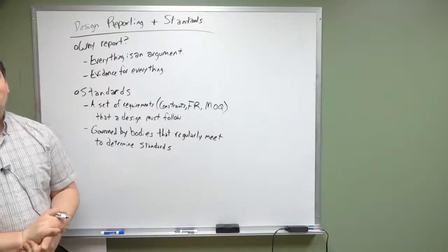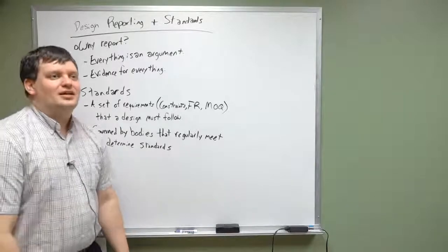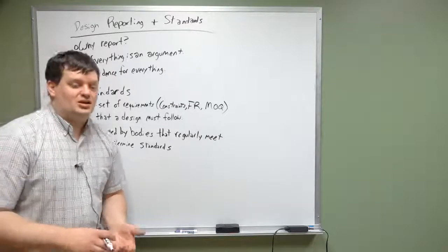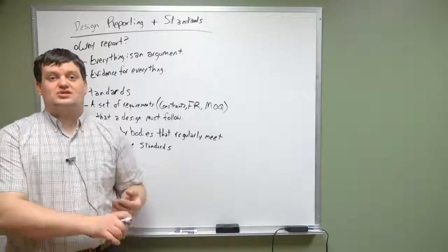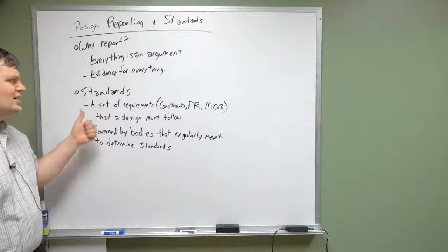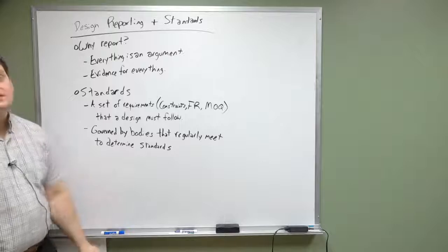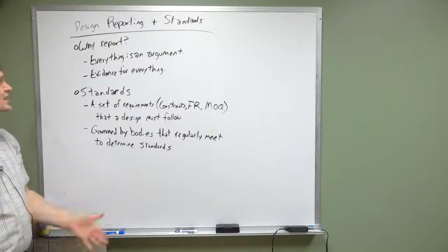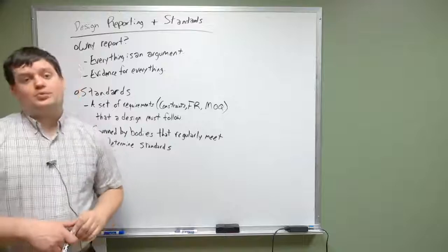So you can't just say, oh yeah, that's a 45,000 pound bolt. How sure are you of it? No, I'm not sure at all. You can't say that. You can say, okay, look at my testing standards. Here, we did testing on bolts from the same batch. We discovered here are the stress strain curves for them. It experiences this peak amount of stress. They actually have that reporting built into these standards to be able to prove evidentiary that it follows the standards. So yes, at the end of the day, standards are present in everything, but they do require a significant amount of reporting.